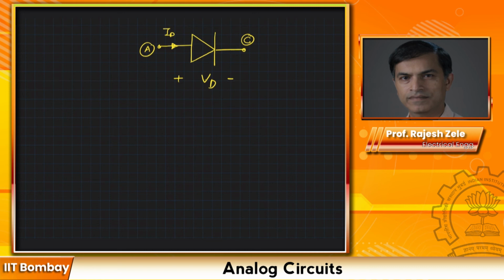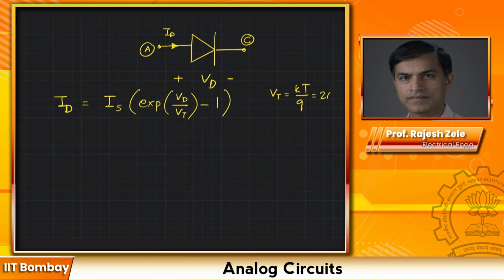So as I said earlier, the diode current is given by I equals IS times (exponential of V diode divided by Vt, minus 1). As I've already mentioned, Vt is equal to kT over q, 26 millivolts at 300 degrees K.